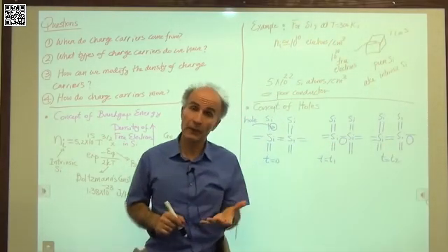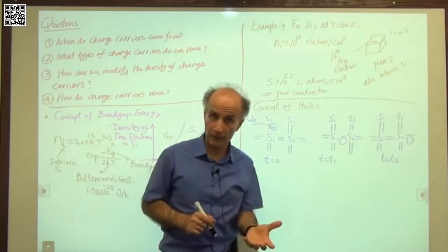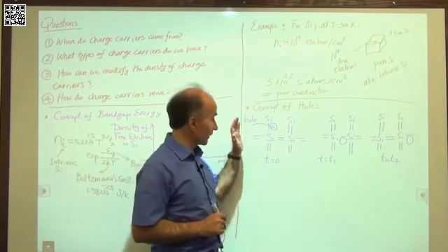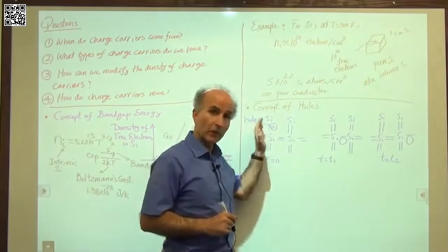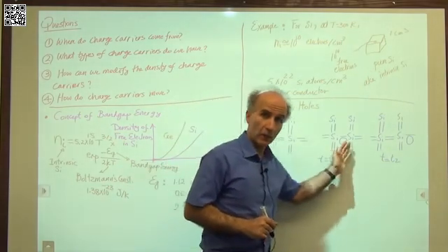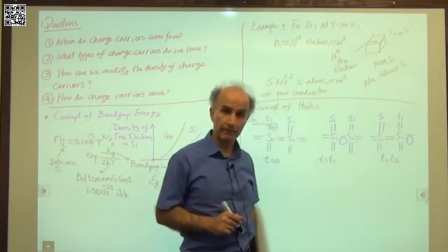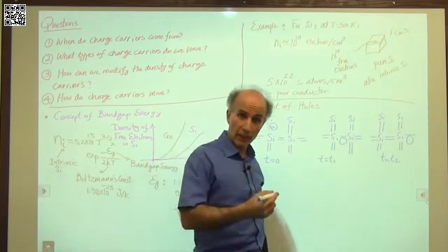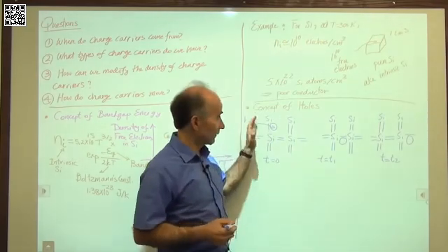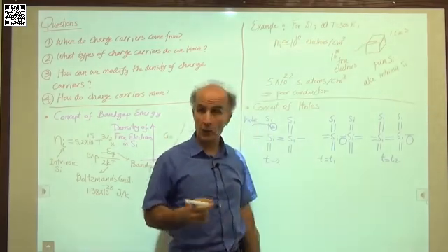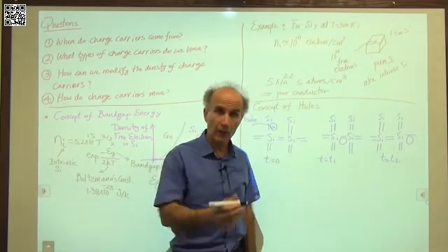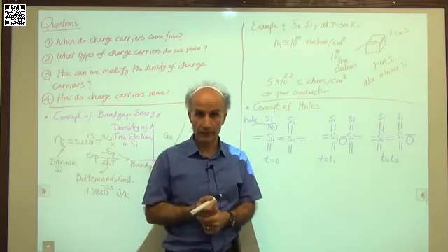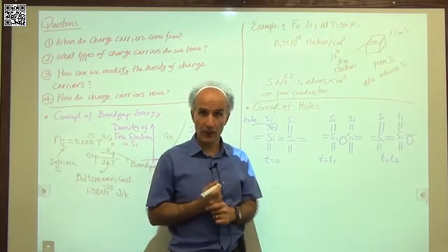And because a hole has positive charge associated with it, we can say that positive charge has traveled from the left side of the semiconductor to the right side as we look at it at different points in time. So we can say a current has been created as we go from here to here. So we say holes are capable of conducting current, just the way electrons are. And that's a very important concept.